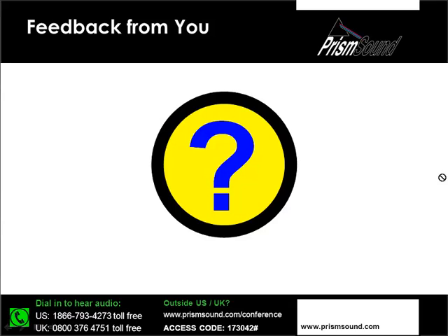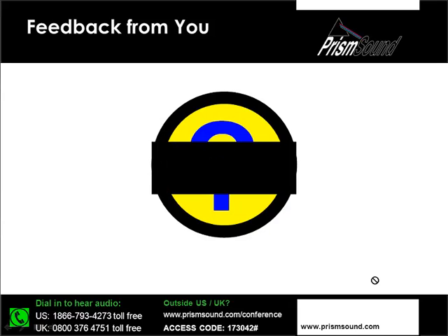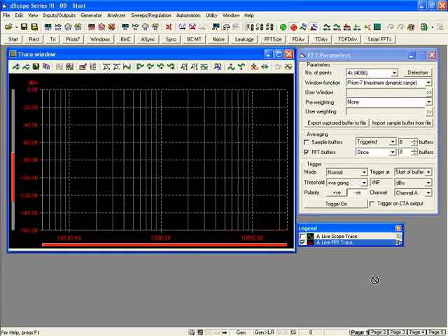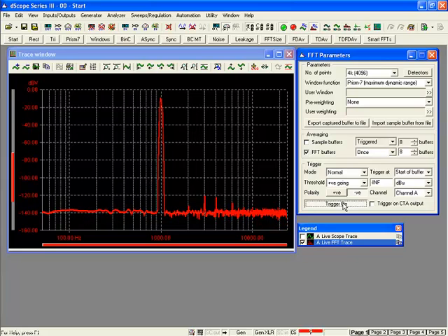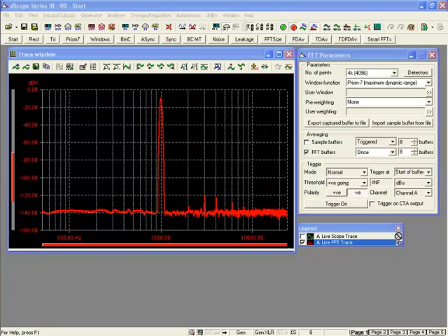So before I go through today's agenda, I'd like to involve you, the audience, and ask you a question. What I'm going to do is make an FFT measurement. I'm not going to explain the background, that will come later. I'm just going to simply turn my FFT trigger on in my measurement system, and there's a bit of averaging. I've now completed my FFT measurement. What I would like you to tell me is what you think this FFT tells us, and specifically I want to ask you what you think approximately is the noise floor reflected in this FFT measurement here.